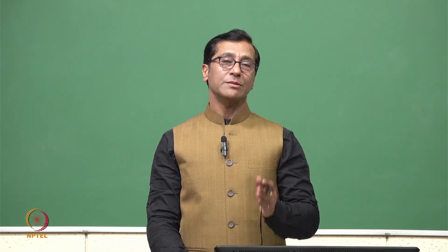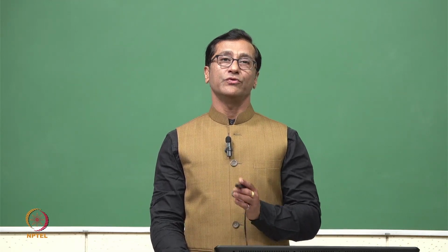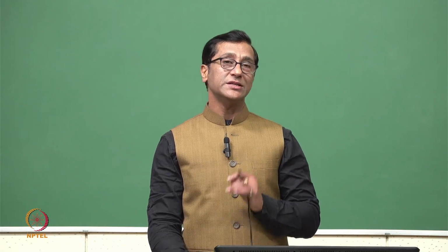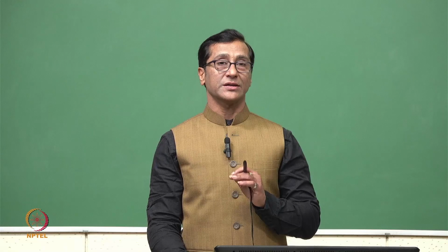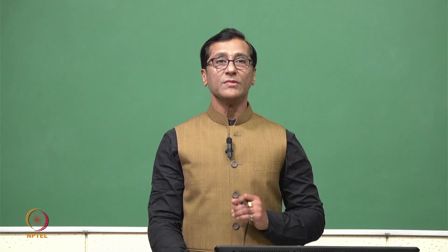If there is some misalignment, we are able to find it immediately and correct it. We did an analysis by misaligning the gear, and we found the accelerated wear was very high. That means even a slight misalignment can accelerate wear by 10 times or 100 times. If we are able to find that in the beginning itself, we can correct it, and the life of the component may be on a higher side.